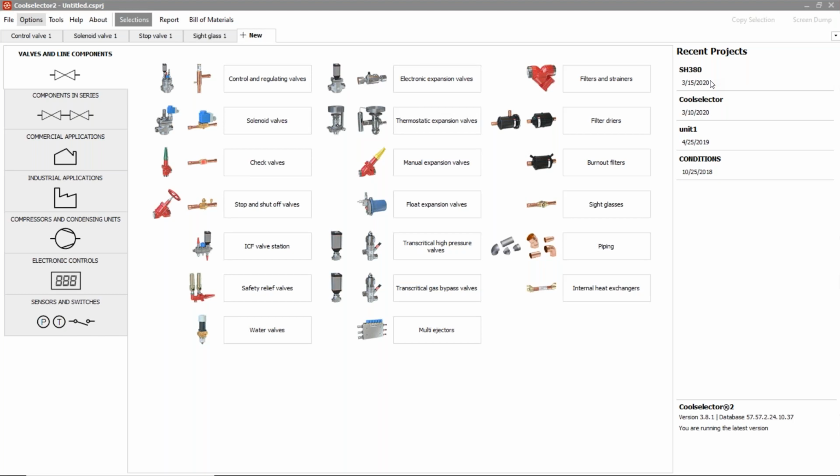And then here you put the surrounding temperature outside the cold room, then the temperature below the floor, and the relative humidity of that room, and if the room has a floor or not. Let's assume this is okay. Then here you have to provide the specific product to be stored. Here we have prepared some.